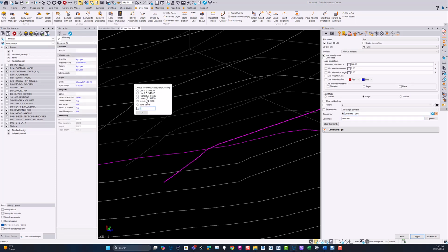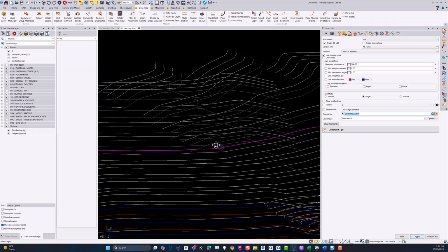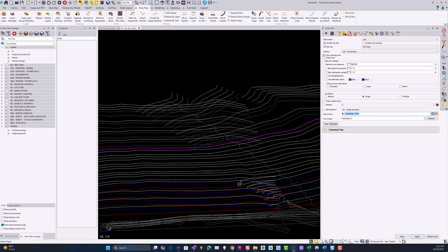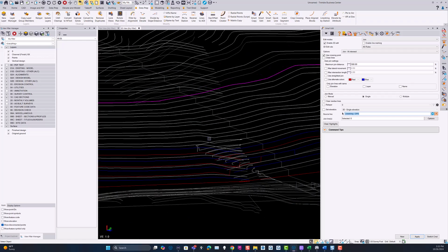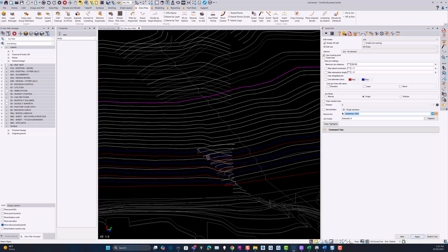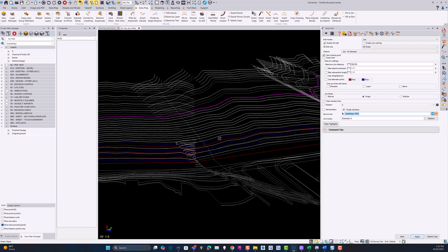line 2, set the elevation and say OK, and then it basically trims and extends the two lines and joins them together. And you can move through this very quickly, and you can see as you do this the benching pattern just evolves and comes to life as you go through this. So by cleaning up these different modes you can do this extremely quickly.